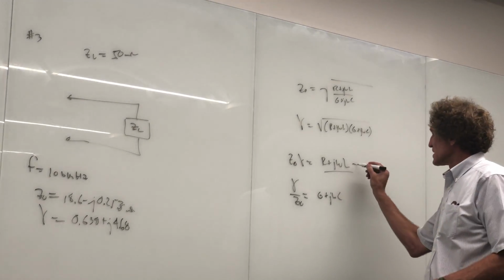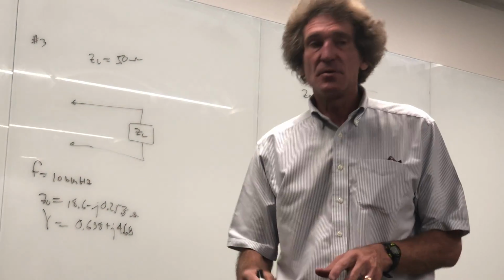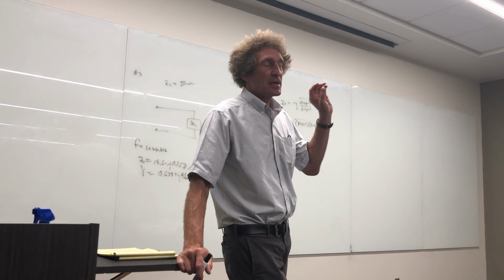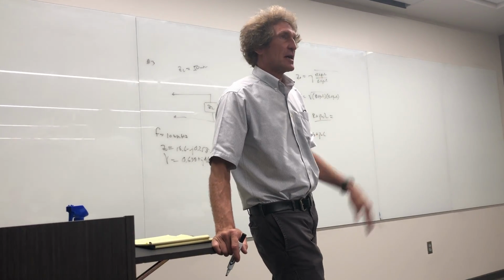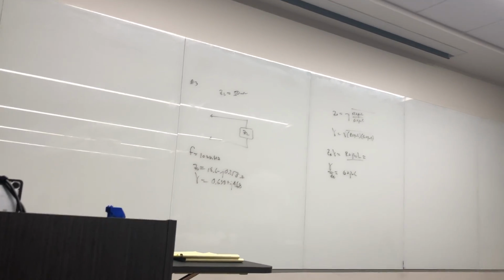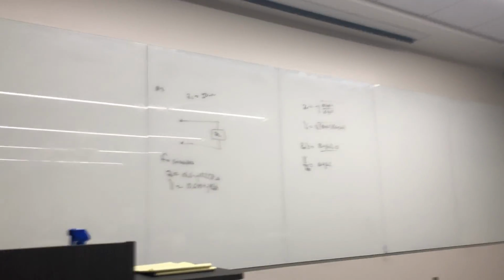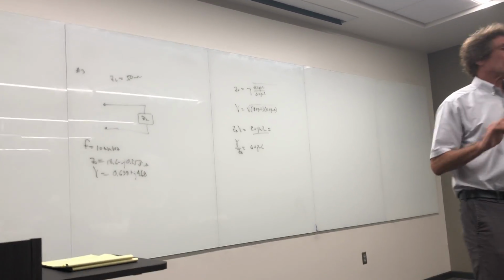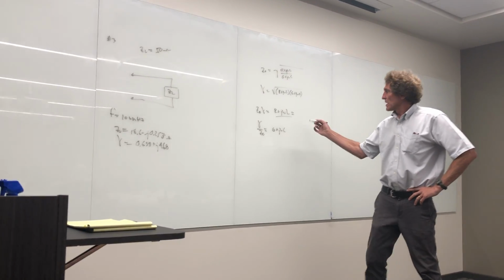Can you guys get your calculators out and use them? I'm going to advise everybody, bring your calculators to class with you. Work out these things when I ask you to, because everybody makes errors in their calculations they think they can't make, especially with that characteristic impedance formula, or the Z in formula, where I have Z naught times the quantity ZL plus j Z naught tangent of beta L over Z naught plus j ZL tangent of beta L. Guaranteed, half the class will mess it up the first time unless you start playing with your calculators. Can anyone go ahead and give me this one?